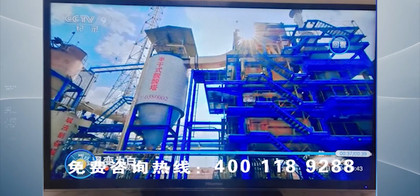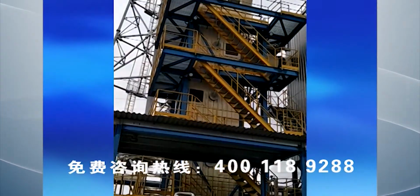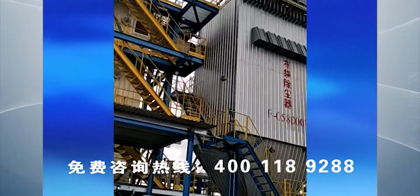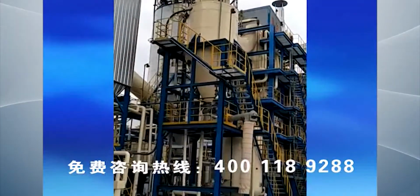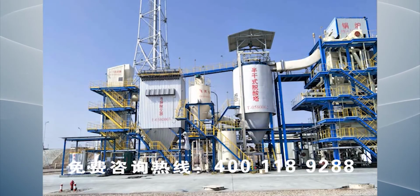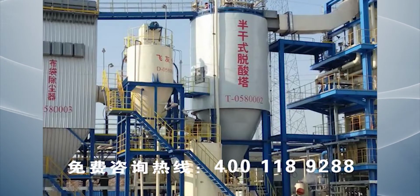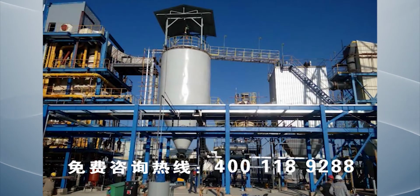On November 23rd, 2017, from 19:04 to 19:43, CCTV specially reported our dangerous waste combustion project in Shenhua coal mines. The process of this project is the integration of quenching de-acidification plus bag dust filter plus denitration plus off-gas discharge. The project has no water washing and no high-salt wastewater treatment. Its solid waste is transported to waste silos by pneumatic conveying.